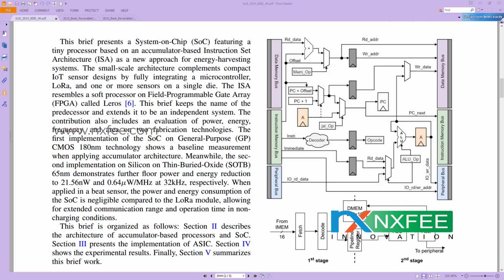Moreover, the use of dual accumulators reduces the instruction cycle time by allowing the processor to handle complex operations more efficiently, distributing the workload across both accumulators rather than processing operations sequentially. So this not only speeds up execution but also optimizes the utilization of processor resources such as the arithmetic logic unit, leading to better overall performance. Additionally, the dual accumulator provides great flexibility in the design of the instruction set and in optimizing instruction pipelines, further contributing to the efficiency and speed of the processor.